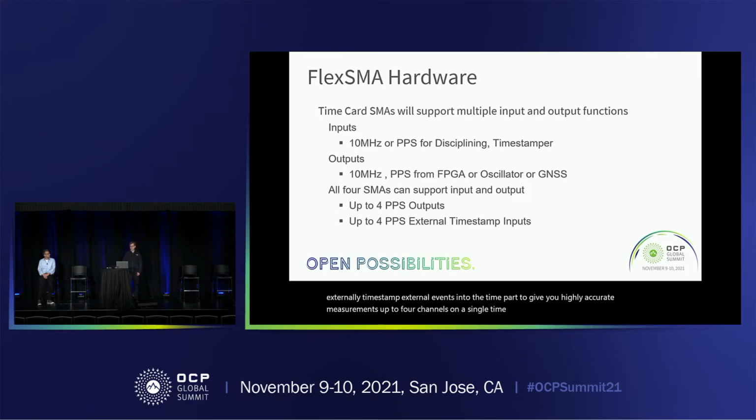For this application, it might not need such a high stability oscillator. It depends on the customer use case. So we'll also have other revisions of the time card with different oscillators available, so different customers can use the time card for their needs. If you don't need the high stability over 24 hours or multiple days, you can use a lower end oscillator, and you can still have access to all these features such as time distribution, time stamping, and general time server applications.